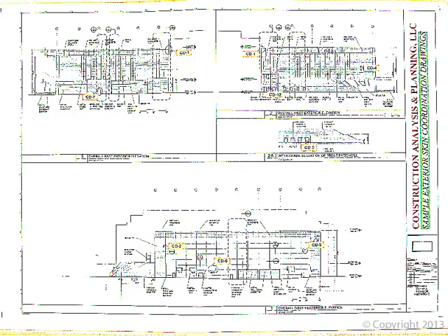CD7 is a flag indicating the head, jamb, and sill of the door frame that needs to be coordinated with the brick facade and the secondary membrane behind the brick facade. I've just noted this as one detail, but you'll actually have 3 different details for the head, jamb, and sill. I would typically log these as CDs 7A, 7B, and 7C. Let's just go over a couple more of these to get the feel for it.